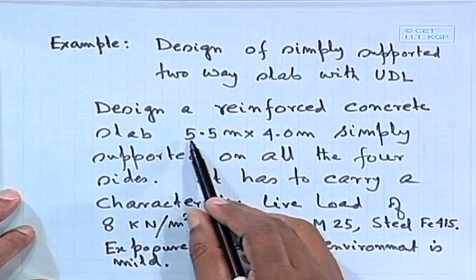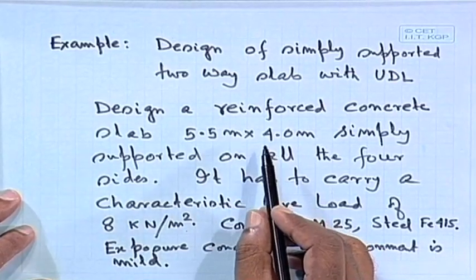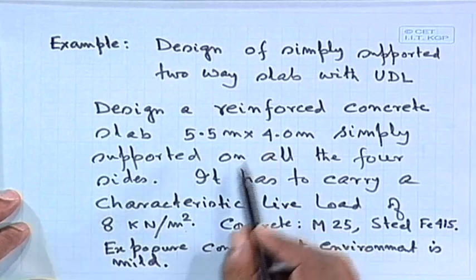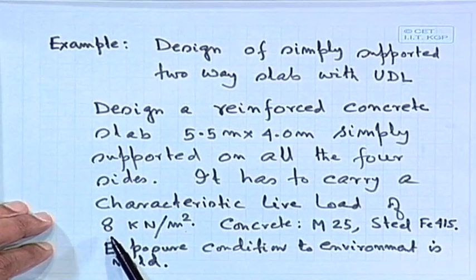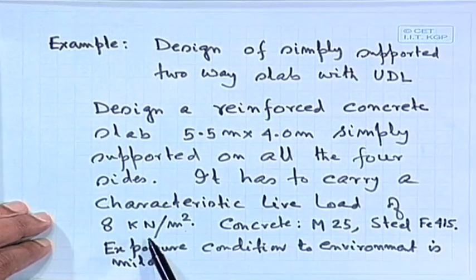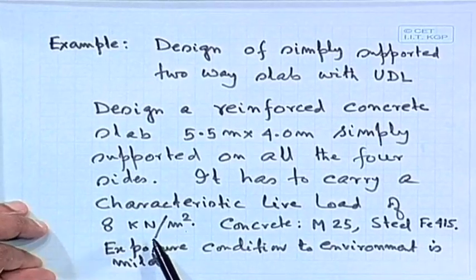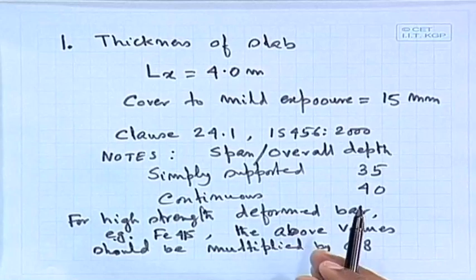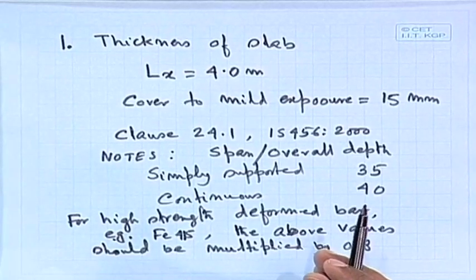So, this is the clause, but let us see our problem. Please note, it is told that it applies to mild steel and spans up to 3.5 meter, but in our case the span is more than that, that is violation number 1. Number 2, it is not 3 kilonewton per square meter, it is 8 kilonewton per square meter in our case. That means we slightly violate that rule.